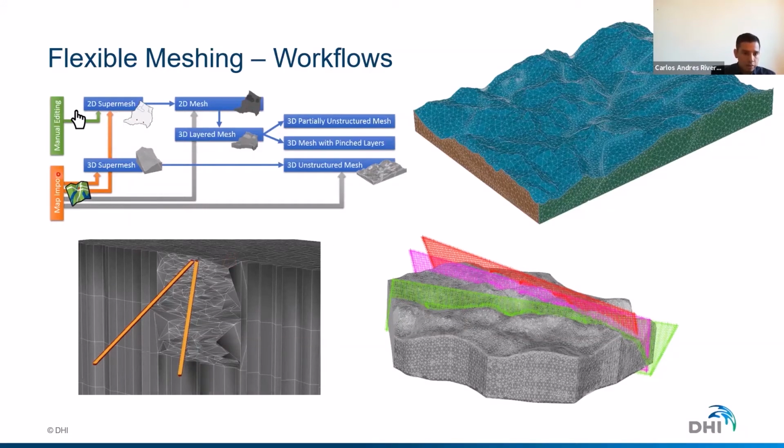If you are in the position that you have a very good geological model, you work with any of our accepted formats, and then we can read your geological data and build a 3D super mesh. And with a couple of clicks, you automatically build a 3D unstructured mesh in FEFLOW.